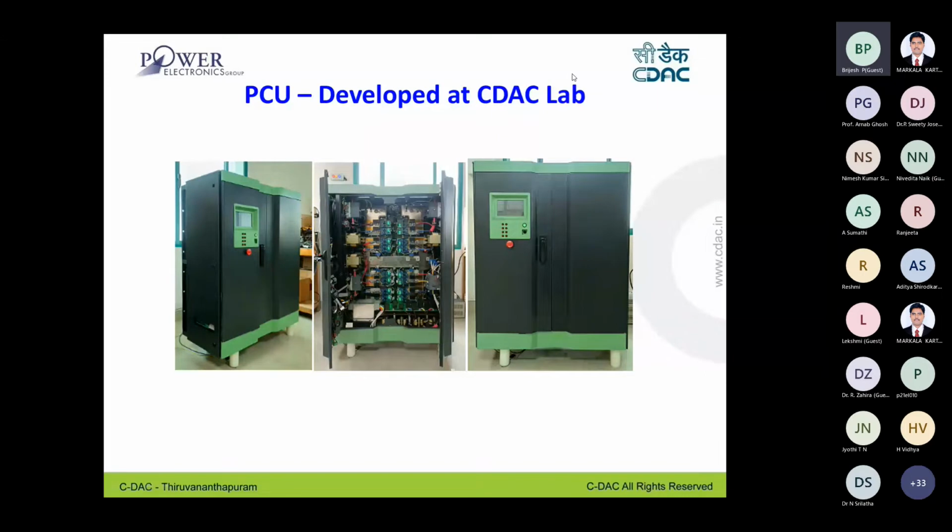It is a power conditioning unit developed at our lab. You can see these are gate drivers and devices, and the transformers and inductors, the magnetic parts, are reduced to a small form factor as it is at 50 kilohertz. We have a graphic touch screen HMI with storage option.